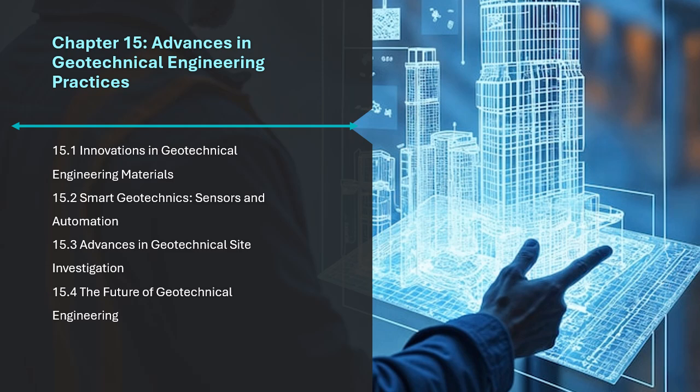Seismic refraction and reflection surveys. Seismic surveys involve measuring the travel time of seismic waves through the ground to identify subsurface structures. The seismic waves reflect or refract when they encounter different geological layers, providing information about soil properties, rock depth, and